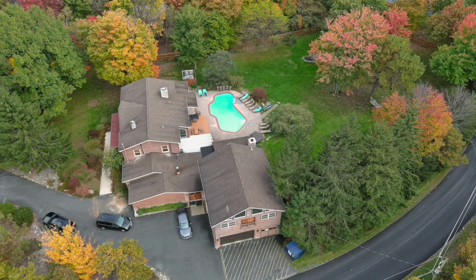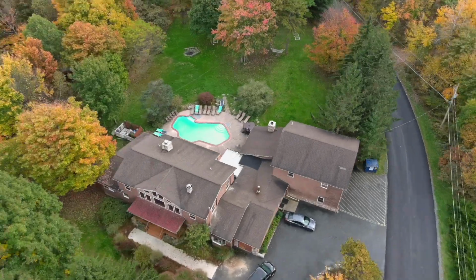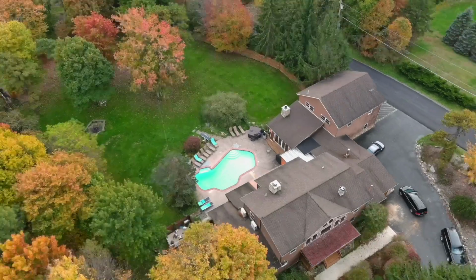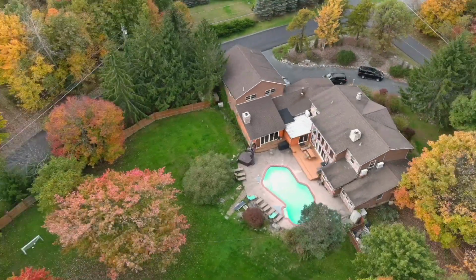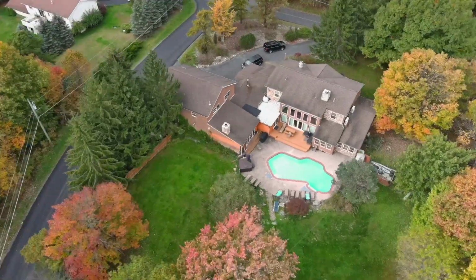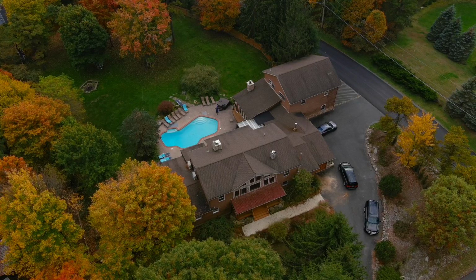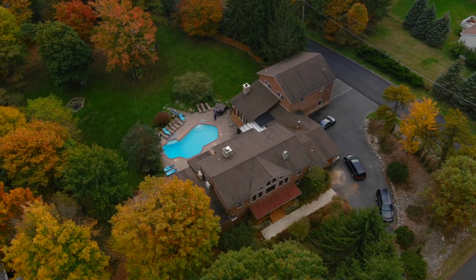Here are some of the photos we took with the Autel Evo 2. Overlap is a term that describes how much a photo is similar to the photo that was previously taken. You'll notice there's a lot of overlap between our consecutive images. High photo overlap is important for creating a good 3D model. If you're flying at 2 miles per hour, take a photo every few seconds.